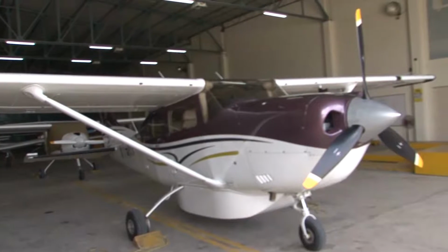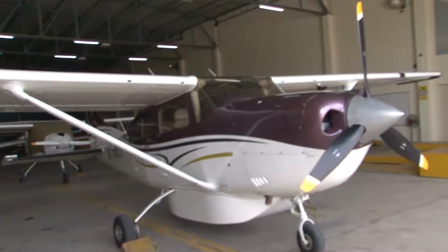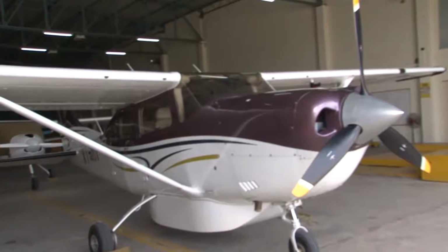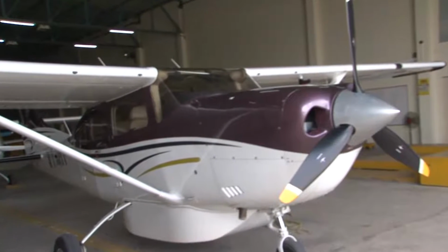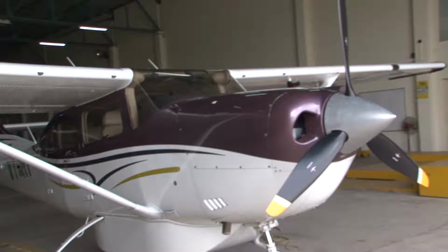And since I now need to know what the wing loading is, I am taking the gross weight of this airplane, Cessna 206, and the gross weight is around 1636 kg. So gross weight is 1636 kg and wing area is 16.17 meters squared. So for me, it's very easy to get wing loading. Wing loading will be around 100, 105, 110 kg per meter squared.